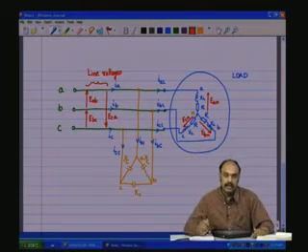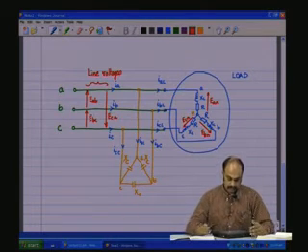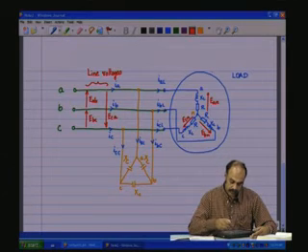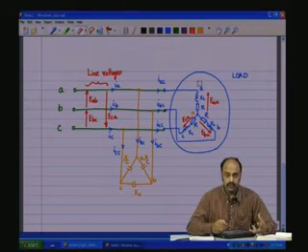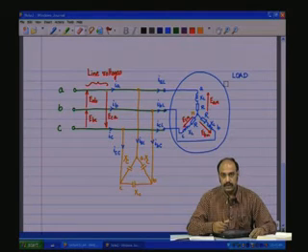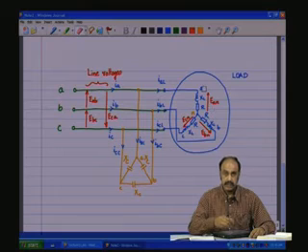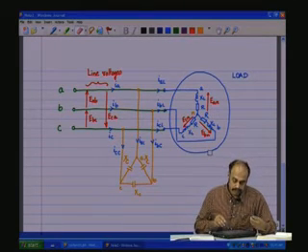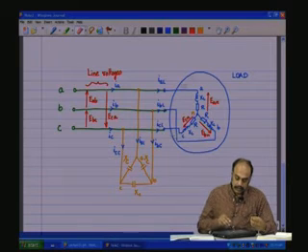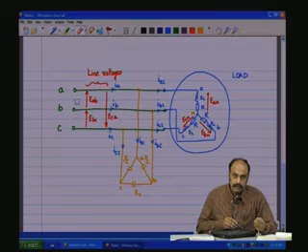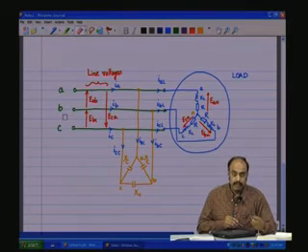So, this is the schematic of a very general 3-phase circuit system, where the actual load is inductive in nature, which is what industrial loads generally are, because most of them drive motors, which are basically lagging power factor loads. If the power to be delivered to the load is very high, then the reactive component taken from the generator can be prohibitively high.